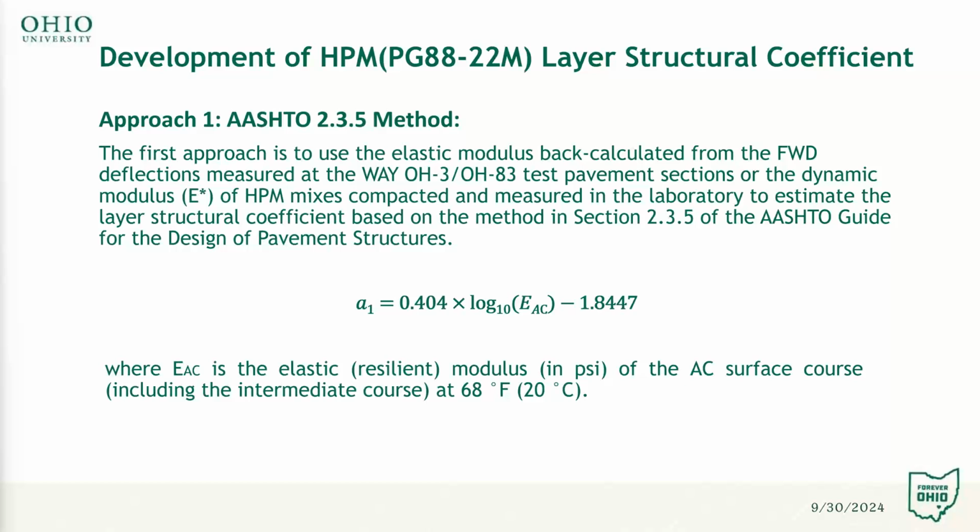So the equation shown here is used to estimate the structure coefficient based on the elastic modulus or resilient modulus of the asphalt concrete surface layer at a given temperature. Next, please.